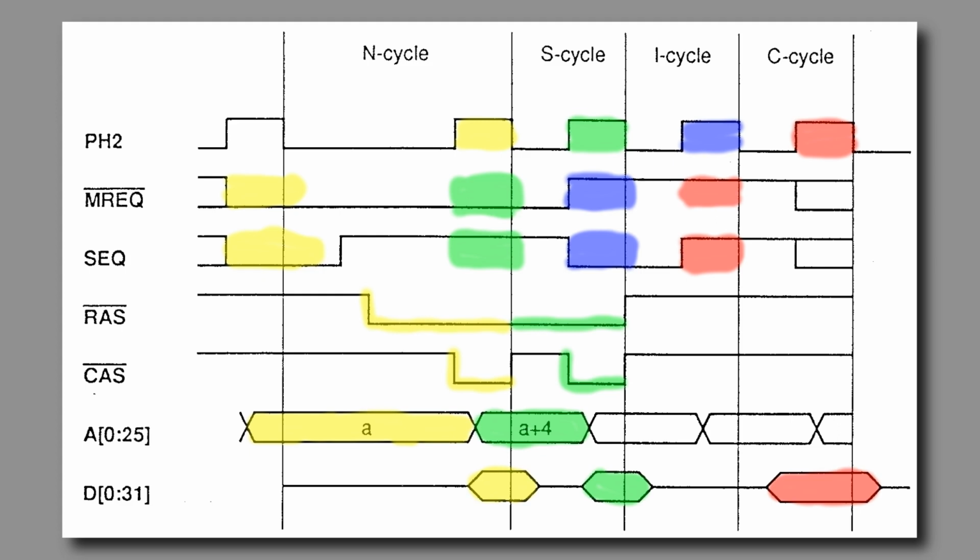And in fact, the mechanism that you have to use for this is essentially to stretch the clock if the RAM needs more time. And in the Acorn RISC machine, the whole design was based around the memory controller actually controlling the clock. The CPU was entirely clocked from the memory controller, and this two-phase non-overlapping clock was all output from the memory controller. And whenever it needed this kind of thing, it would just pause the CPU for a bit.